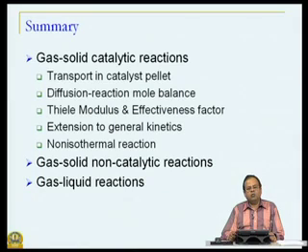Firstly, we identified that there are several steps before reaction can take place: transfer of reactants from the bulk to the surface of the catalyst, then from the surface of the catalyst to inside the catalyst, then adsorption of the reacting species onto the surface, chemical transformation of these active adsorbed species into a product still adsorbed onto the catalyst surface, then desorption of the product from the catalyst surface, its travel backwards from the interior of the catalyst to the surface, and from the surface eventually into the bulk.